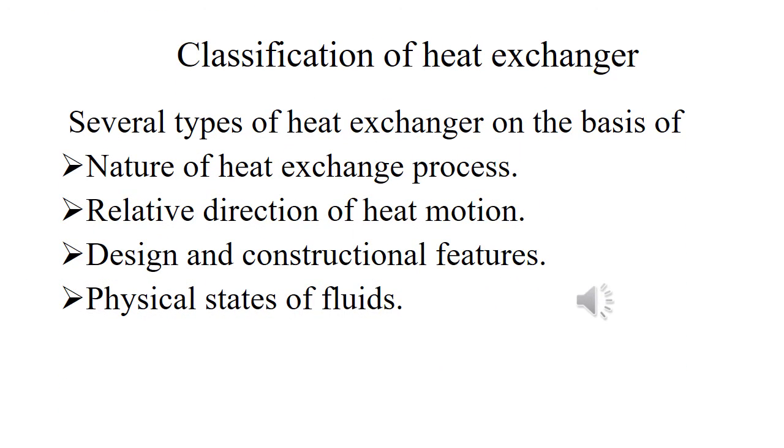Now we will see how heat exchangers are classified. Heat exchangers are classified on the basis of: number 1, nature of heat exchange process; number 2, relative direction of heat motion; number 3, design and constructional features; and number 4, physical state of fluid.